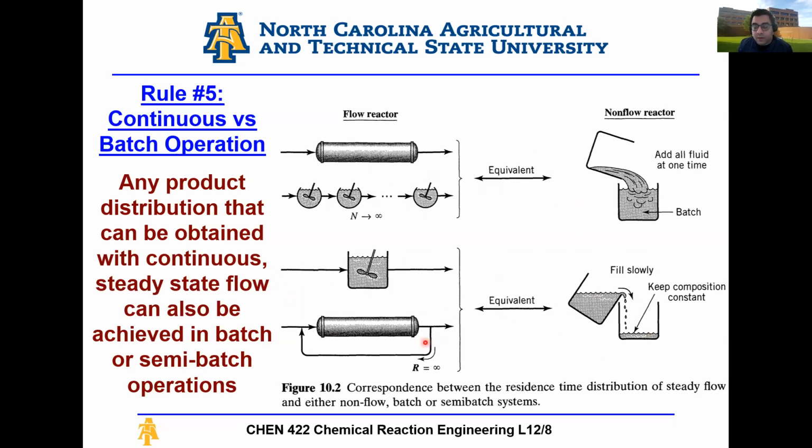However, if you're doing a pharmaceutical process, for example, your volume is very low and you want to maintain very high control of the reaction, then maybe you want to use a batch reactor where you control the system much better than having a PFR with recycle. If you're on an oil and gas plant where you're just trying to pump out chemicals, or refine some crude oil, and you want to desulfurize through a reaction system, or you want to coke a system or whatever, then a batch reactor doesn't make sense. Your volume is too high and you have a very high concentration, so you want to use a PFR to minimize your economics. So other considerations start coming into play now.